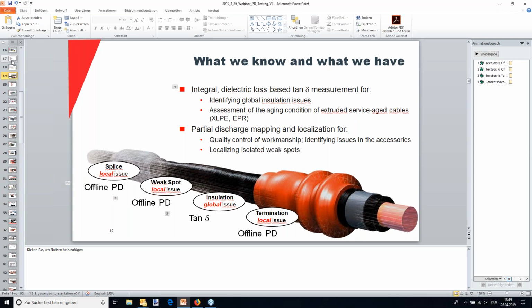I know it sounds counterintuitive, but the best thing is always to bend the cable a little bit back and just have it suspended in air, with your sphere of 20 centimeters around so you don't get much influence. That's really the best way to have the cable.